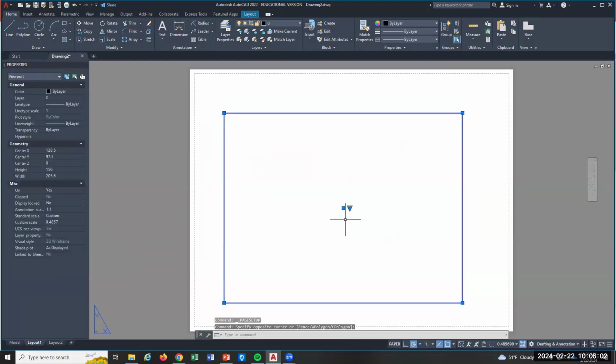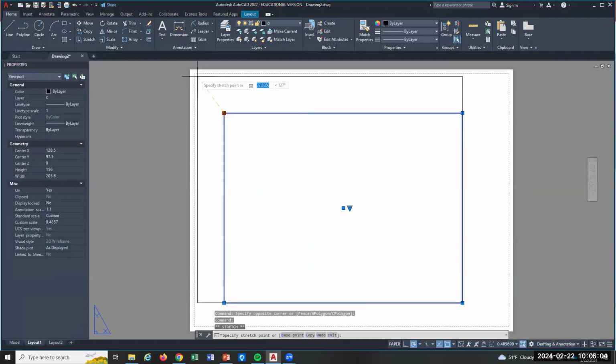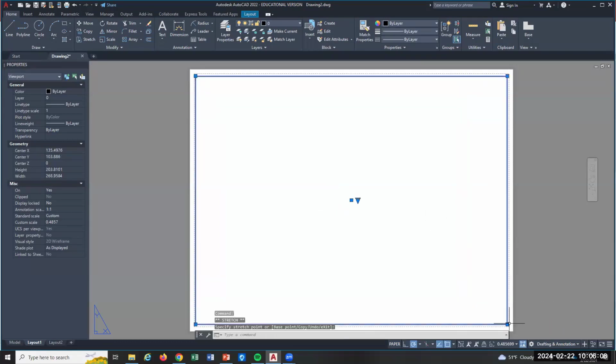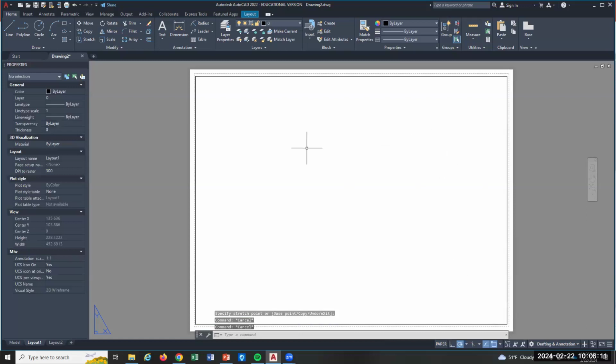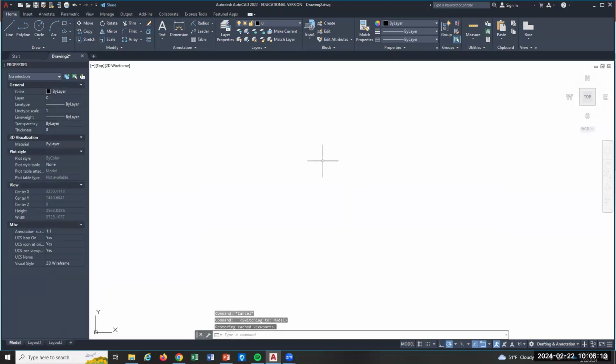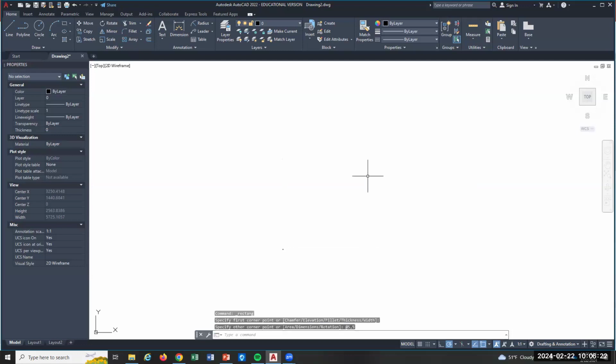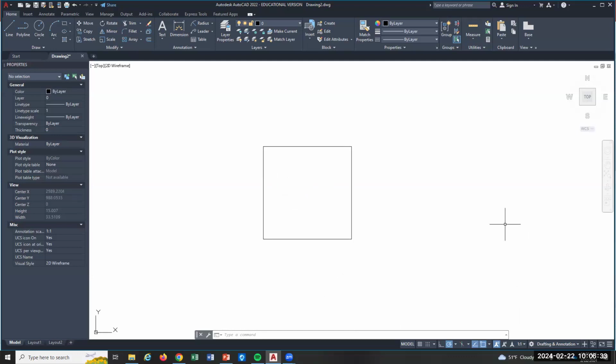Then these are called viewports. If you don't remember that, you want to drag those out and get those as big as possible, because that's your drawing space, right? So now you have a nice big drawing space. Whatever you draw in here, I'll just throw a rectangle on that is 5,5. Remember, what are the units? Millimeters. Yeah, that's why it's like disappeared on you, right? There it is, 5,5. That's 5 millimeters by 5 millimeters.